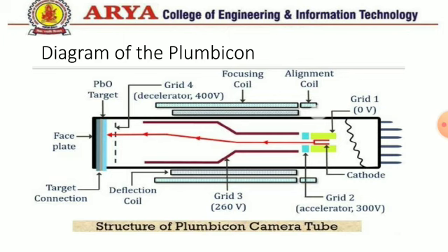So because of this non-leaky capacitor, it has a few advantages compared to Vidicon. This Plumbicon has a PIN diode, with P on which we are bombarding the electron beam, and I sandwiched in between P and N. N is connected to the target voltage, and the positive of the target voltage is connected to N, meaning this PIN diode is in reverse bias.